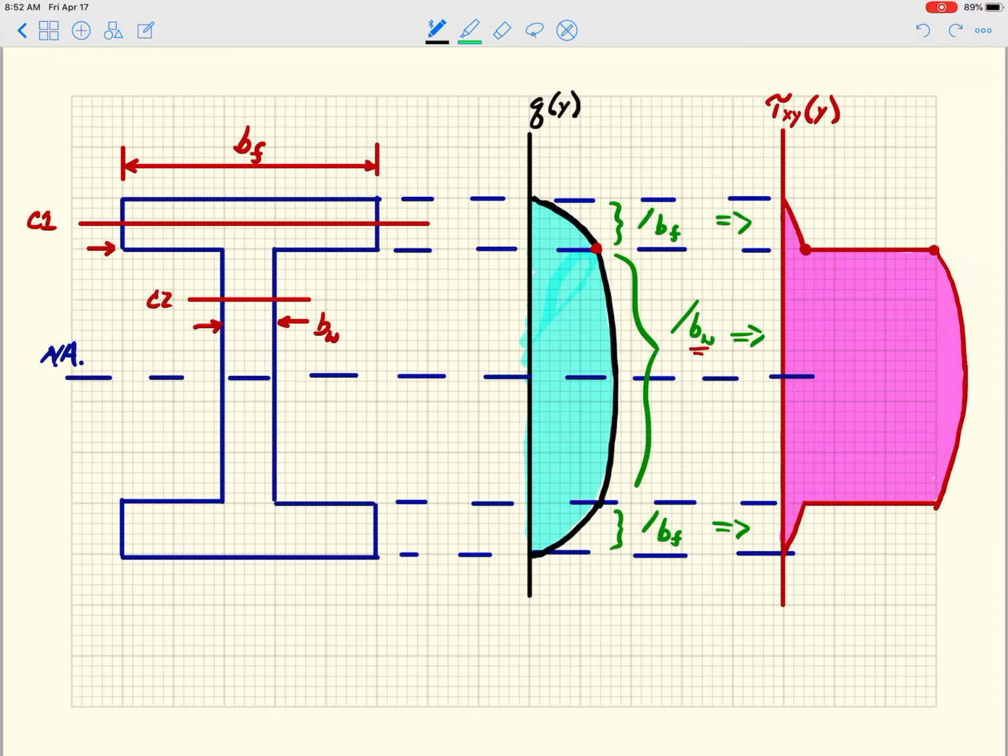Okay, so in terms of where the shear is actually carried, you could look at this and say, well, it's sort of blended between the flange and the web, a smooth transition there. But again, that's shear flow. And materials, although they feel shear flow to a certain extent, as we discussed before, you've got to divide the force by an area to actually understand what the material is feeling.